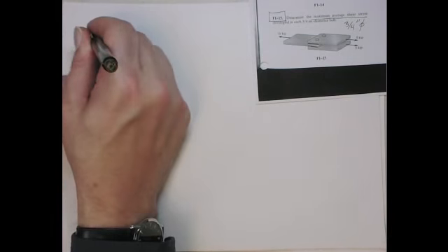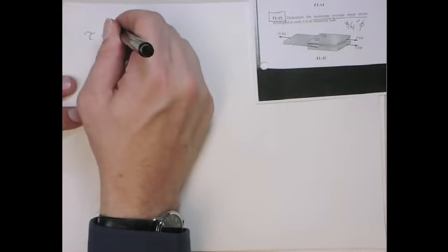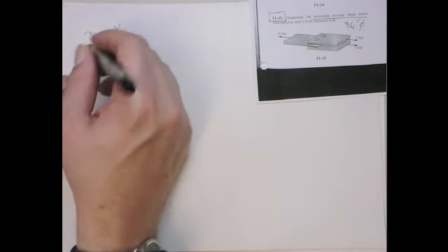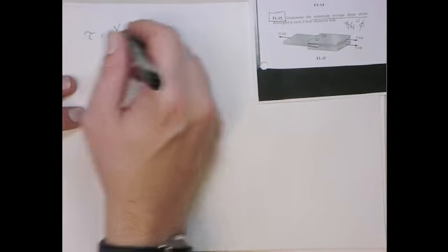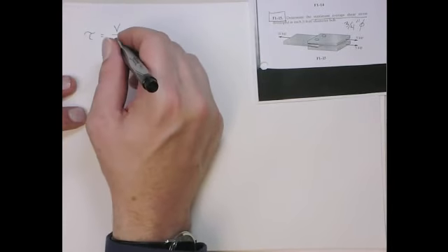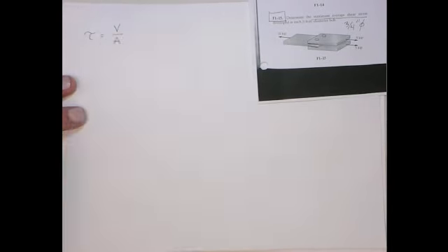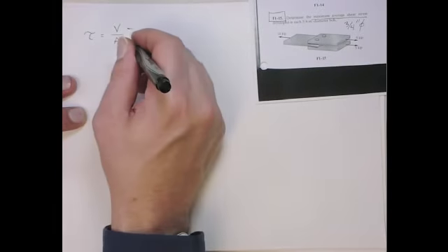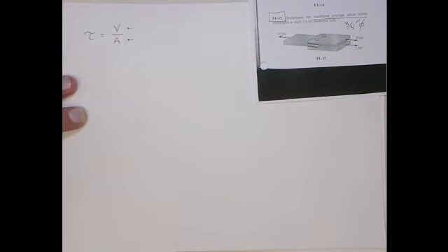Okay, so with this problem, again, we need to get the maximum average shear stress. It's the shear force acting over the shear area. And so the question is, what is the shear force on each bolt, and what's the appropriate area?